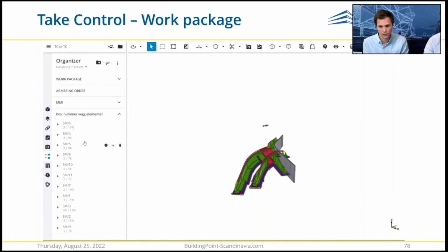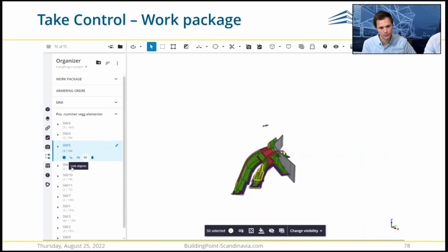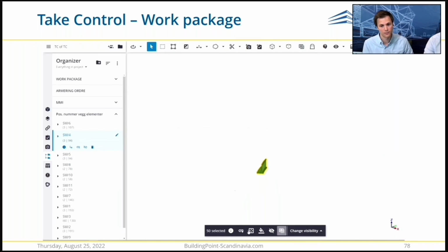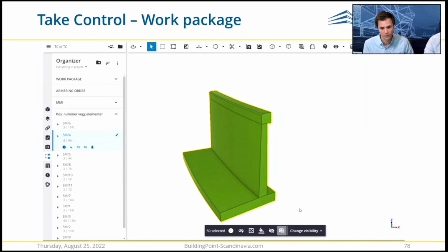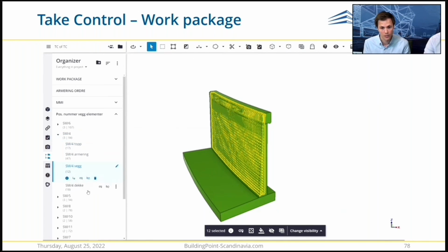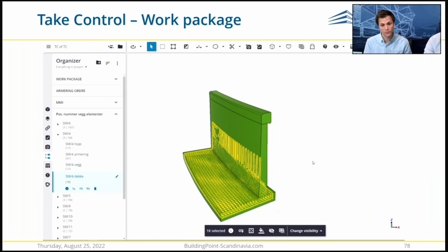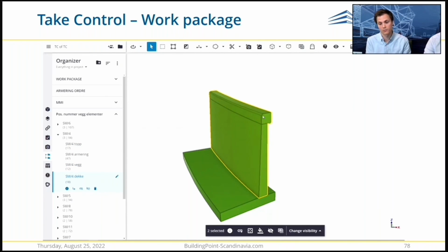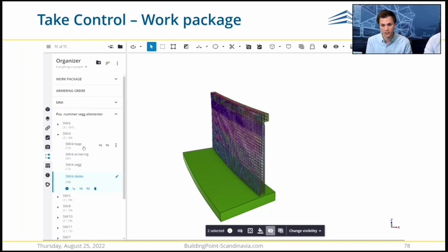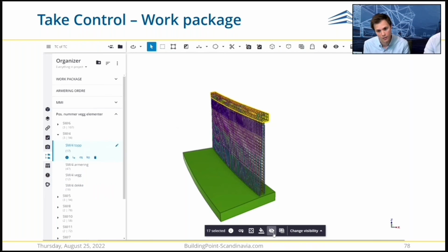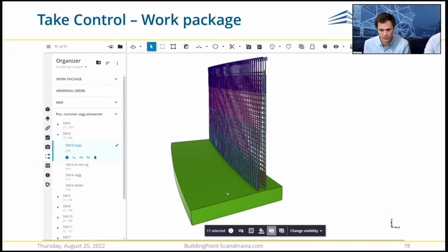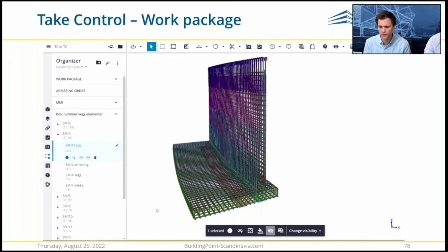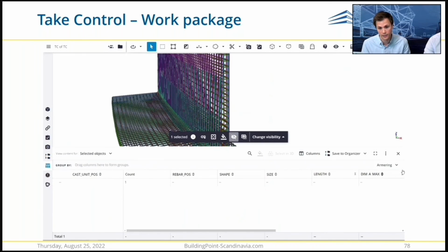Finally, an example of a custom model breakdown structure where, based on the part of the culvert wall, we have one group per part, and each part is breaking down into relevant subgroups, and we can keep breaking it down to concrete and every rebar in the foundation and split it up more and more. The idea is again to have relevant groups of objects selectable with one click so that we can view their properties or hide them easily.